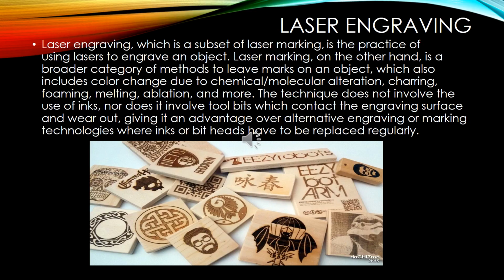Hard papers and fiberboard work well. Linty papers and newsprints are like softwoods. Fur is not engravable. Finished leather can also be laser engraved with a look very similar to hot branding. Certain leaded rubber compounds can be laser engraved. For example, this can be used to fabricate inking stamps.